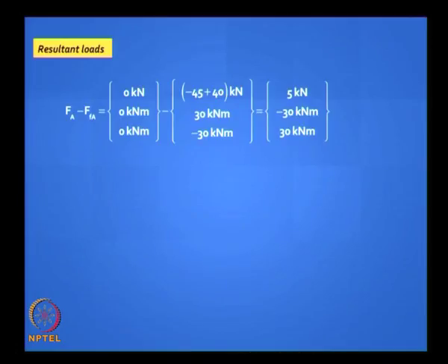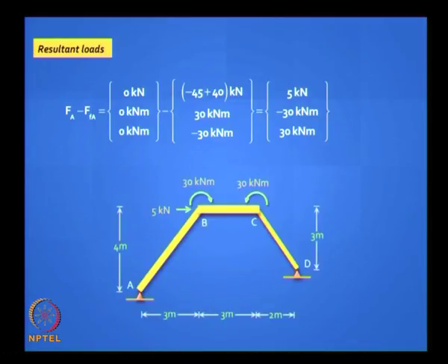Okay, to the left you are right, but when you find the net loads you have to oppose everything, you put a minus. Have you got it? So that's it. Look at this, it's completely different from what we did earlier, and you are going to get the same results. You see, there are so many different ways of solving these problems, but sloping legs problems are tricky, they are notorious. Students generally make blunders, practicing engineers do it, but luckily for you today you have nice